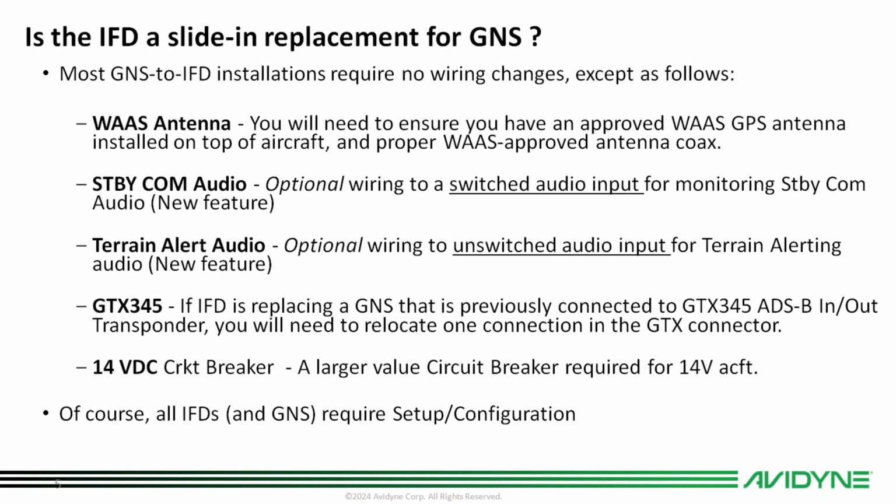So that has to be wired to your audio panel. This was not a function of the GNS originally. We also have terrain alert audio. This is another one of those optional wiring. So these also go to the audio panel, but have to go to an unswitched input for the terrain alerting